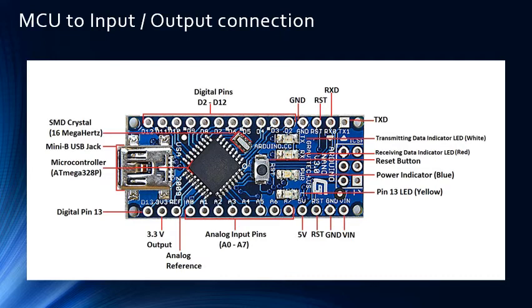But if you want to reset the microcontroller from an external button, then you can connect the button to this reset pin here. And these pins are for digital input or output. This one is for analog input, and that one is for communication. I'm going to cover them in detail in the next slide.